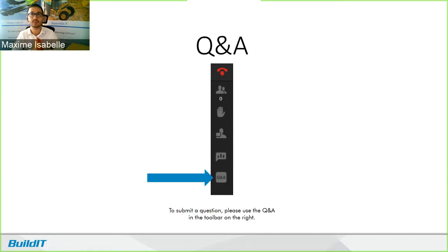You simply hit the record button and walk through the steps, and it records everything, and then you have your process, ready to run on that single part. Now, if you want something that can be adapted for other similar parts or devices, where a lot of things can change, it's a question of using the search function that I mentioned earlier. You can have a search function so that it'll use all surfaces of the CAD instead of a specific set of surfaces. These kinds of things.